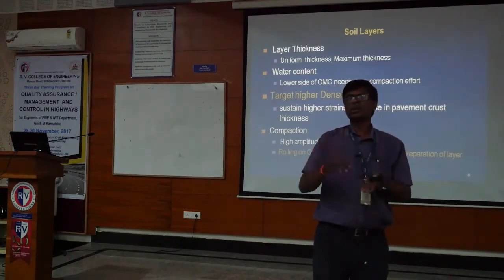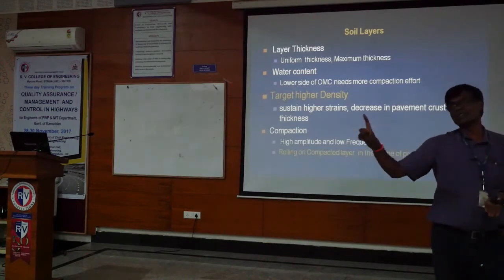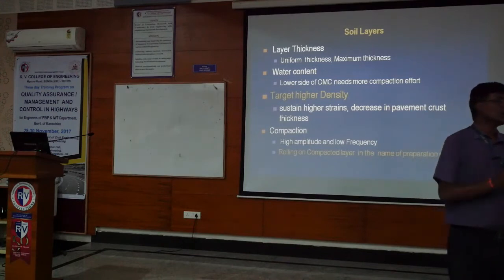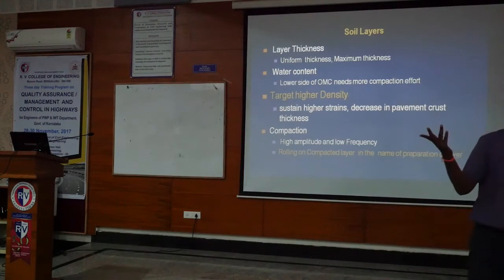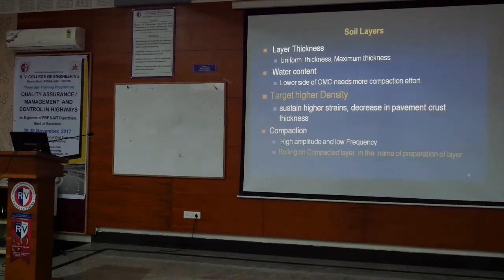Loose thickness is in the range of 250, 260. And 260 is also not constant. 260 or 250, that is confusing. I always take 30% loose and place 260. No, we don't know. Many times if you compact the 260 loose thickness, we may not get 200, we may get 210.